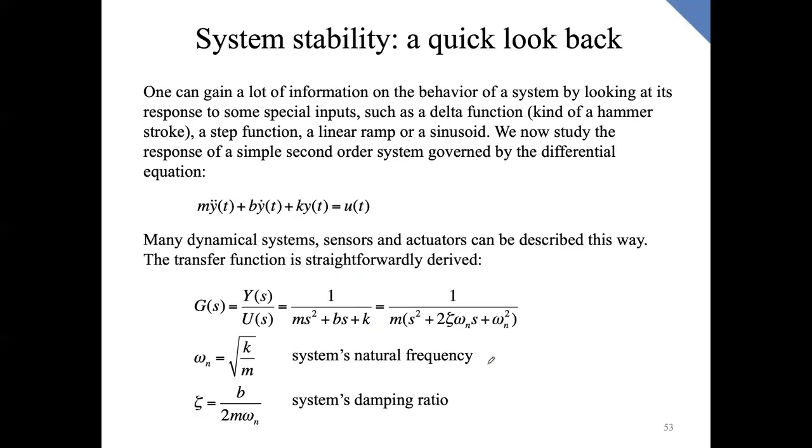Tomorrow, we are going to have a quick look at the stability of a spring-mass problem with a damping. And we are going to see that the same conclusions you draw for that case are similar for the system with a PD controller. The main conclusion is that if you have a constant disturbance, your theta desired is not going to be reached. Your final theta will not converge to your theta desired. But that will be clear tomorrow.